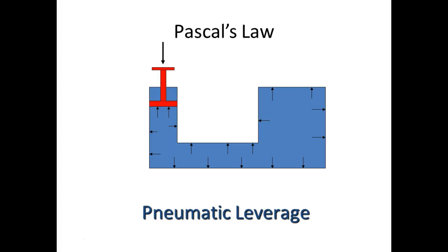So that means if I came over here and pushed down on top of that thing, what pressure would be on everything, on all the walls? What would I have to know first? I'd have to know the area. Exactly right. I'd have to know the size of this piston right here. Now, unfortunately, pistons are round. Everybody understands that. So when they give the size of the piston, what do they give it in? Well, over here we give it in inches.